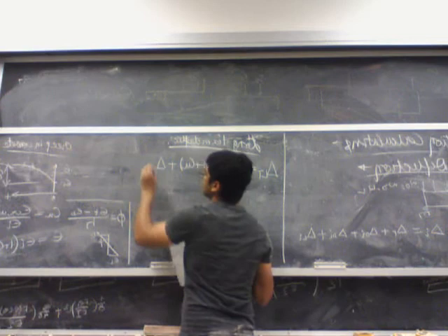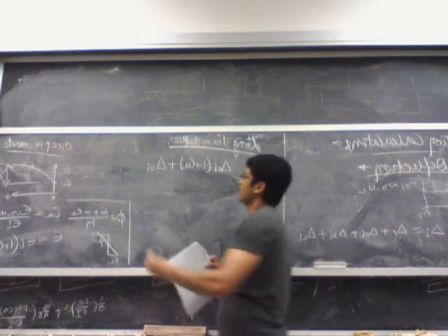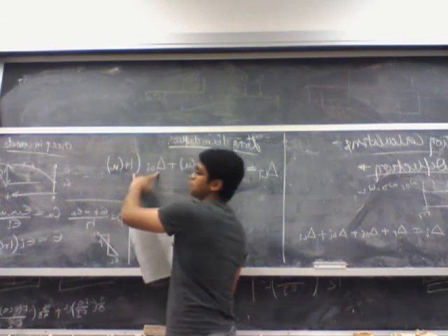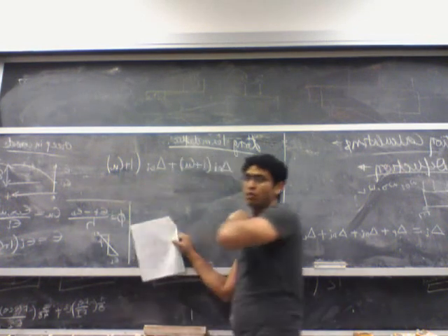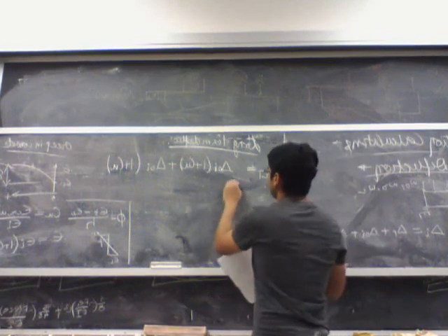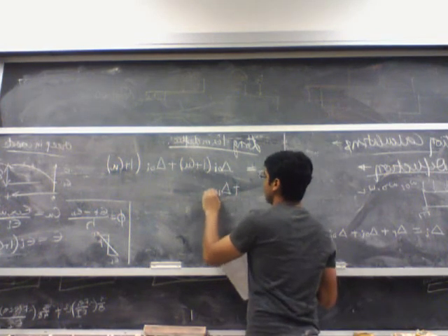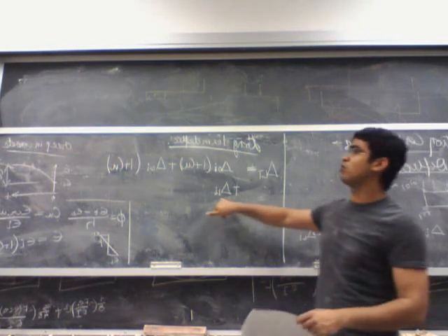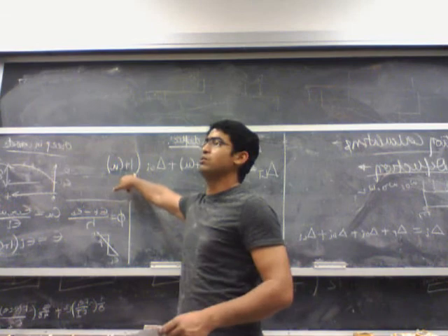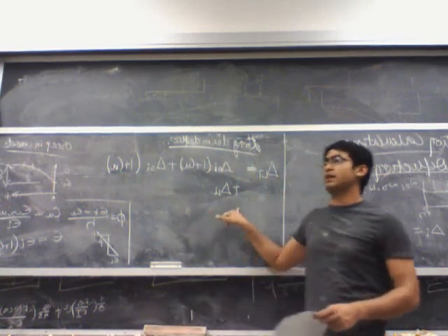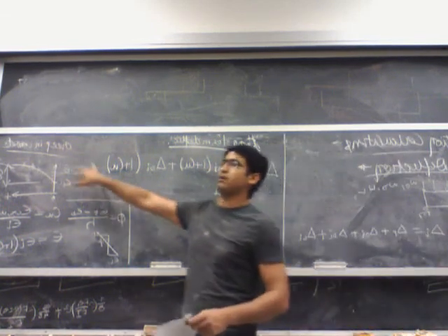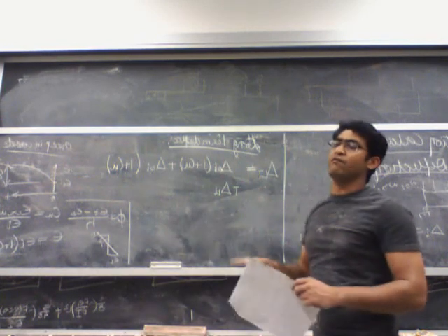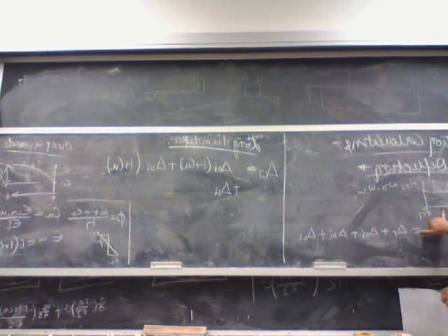If I have an instantaneous deflection of delta Di, I'll just multiply it by 1 plus Cu, and this gives me the long-term deflection due to the dead load. Plus the third term is delta instantaneous due to the live load. Again, as I said, I don't multiply it by the factor 1 plus Cu, because live load is not a sustained load. So it's not applied over a very long time. So I have accounted for everything except for the deflection due to the pre-stressing strand.